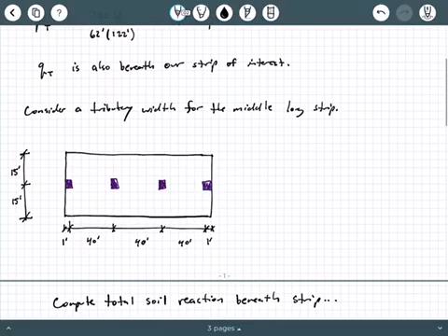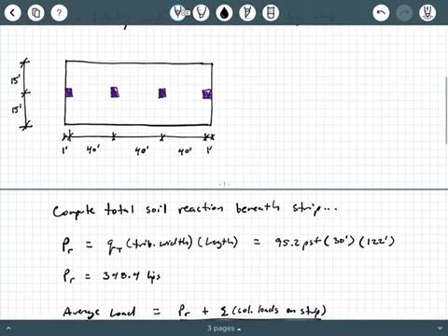Now, here's where we have to be careful, okay? This procedure does not account for what's called shear force between adjacent strips, okay? So when we separate a mat out into different strips, there's technically going to be this kind of discontinuity between adjacent strips where you're essentially neglecting shear force, okay? And because of that, you have to make some adjustments to your pressure calculations. Otherwise, your shear and moment diagrams won't close properly, okay? So I'm going to take you through a couple of quick steps to do that.